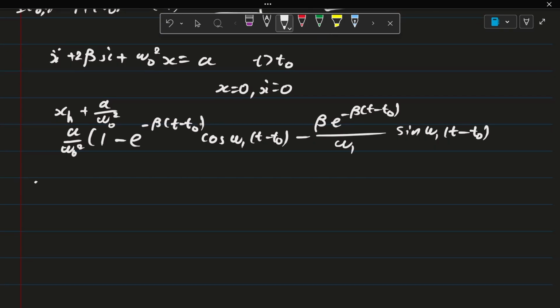Now we could do the same thing for the impulse function, but instead of doing the entire thing one by one like before, we can use the principle of superposition. We know that the impulse is just h(t0) minus h(t1). So we could just use the solutions that we know, which correspond to initial conditions of 0, 0.